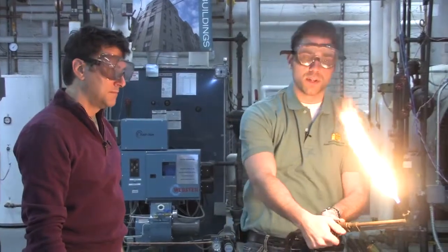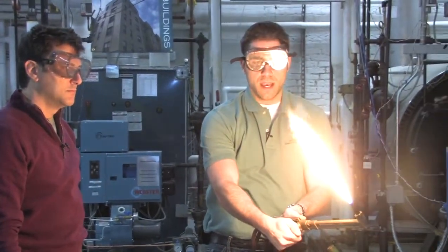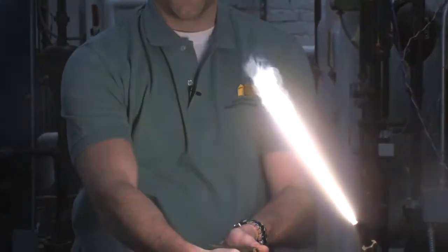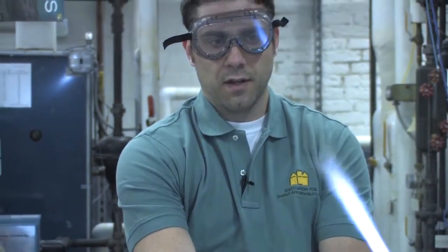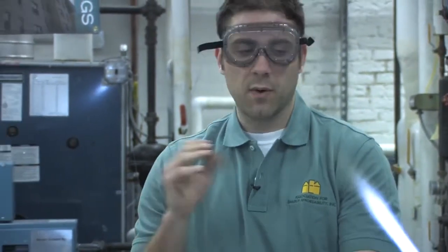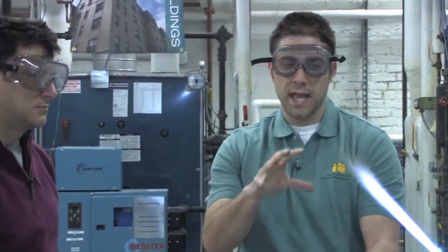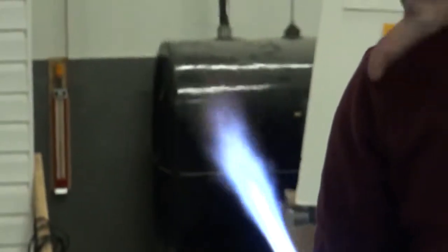So in this case, now I'm going to start to add the oxygen in very slowly. And as I add it in, you're going to start to see the flame take shape. And it's going to get a lot hotter and it's going to get a lot cleaner. So same amount of fuel. Same amount of fuel, but now we're adding more oxygen into the process. As we add it in, we're going to get a hot, tighter flame. And this way now, there's not that soot that's flying around it. Right. You get a much better burn of the actual fuel.